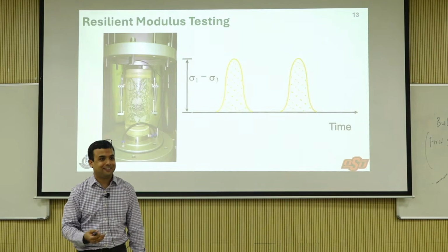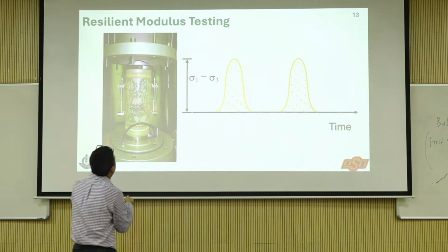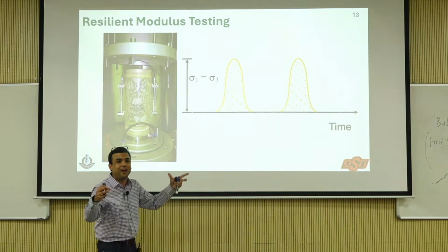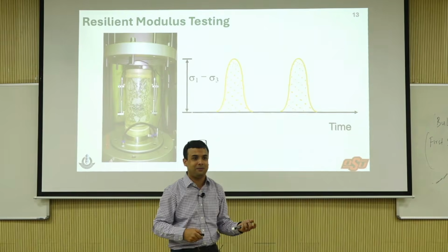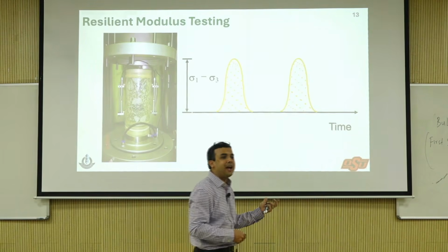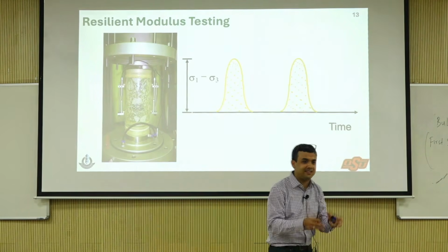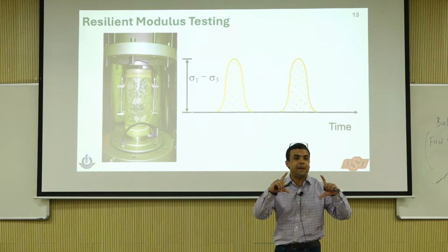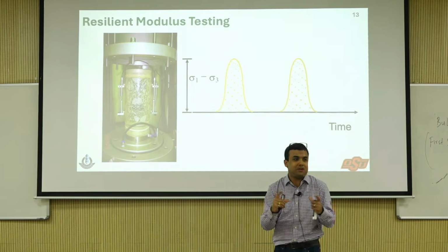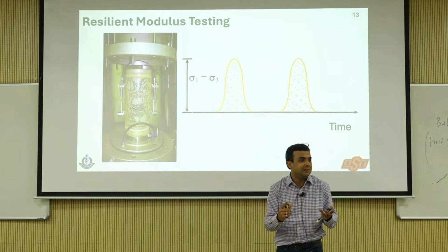Your LVDT will break, because you are on the sample here. It's going to bulge. You're going to ruin your LVDT. Your advisor is going to be extremely upset at you, right? So what I'm trying to say is, for shear strength testing, you usually don't do on-sample deformation measurement because your LVDT is going to break.